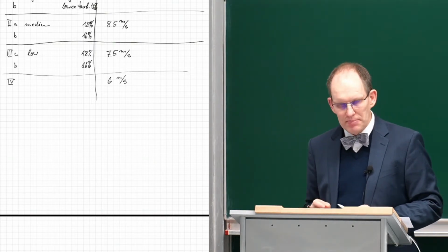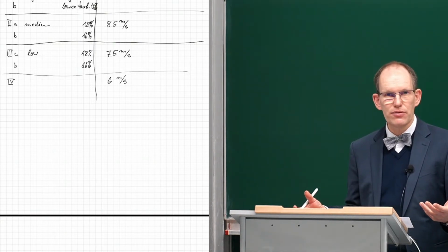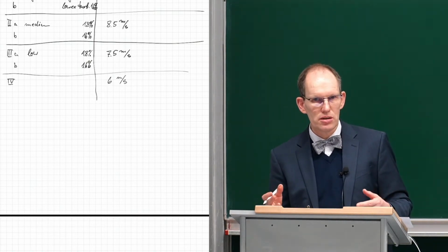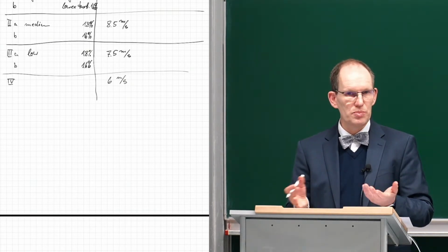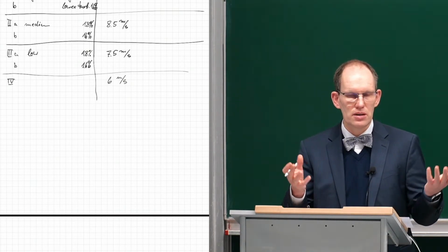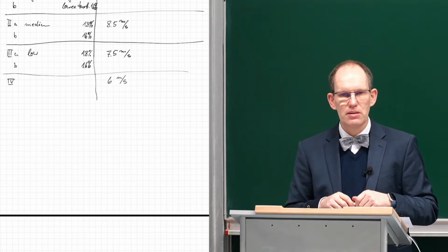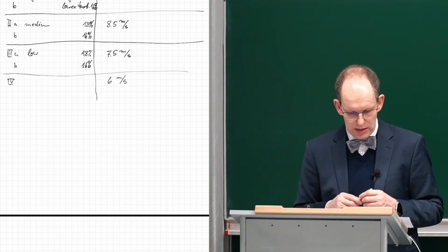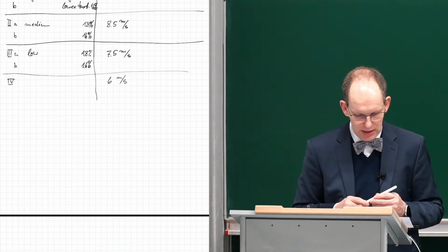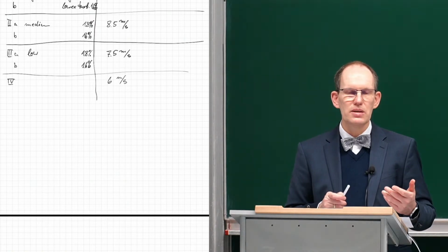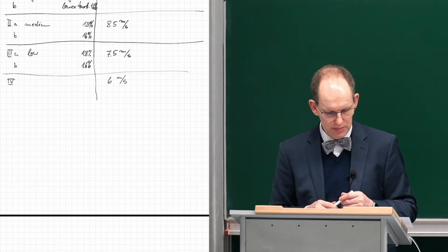Okay, well, of course, such a windmill needs to be designed for extreme wind conditions, so its survival needs to be specified for much higher wind speed. And the figure that's used is the 50-year gust, the extreme 50-year gust. And what one assumes is a factor of 5 to 7 times higher. Yeah?